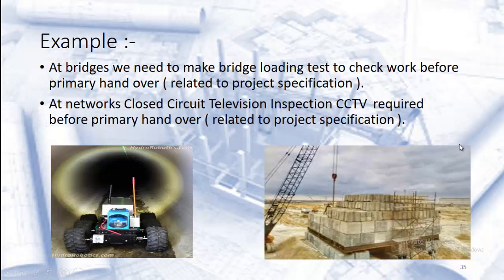The pile loading test is done on a non-working pile or on a working pile according to the specification. This is an important test that must be done at the beginning of work to check the pile load, which has an effect on the distribution of piles at rafts, pile caps and others.